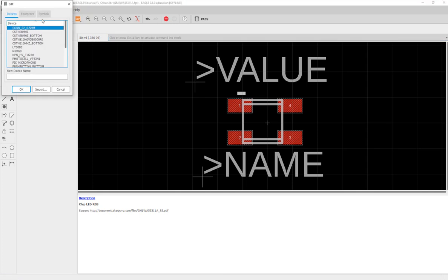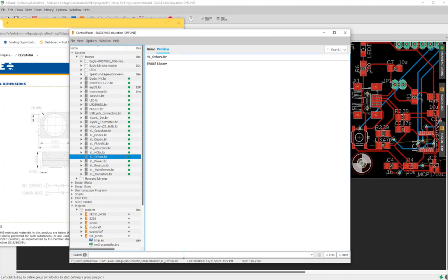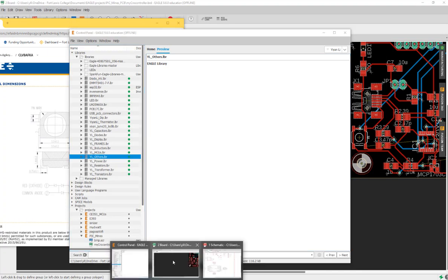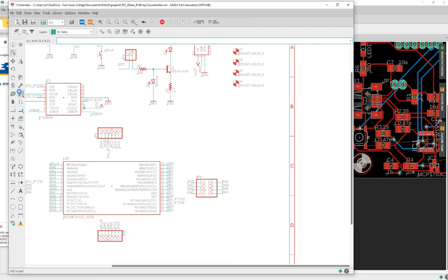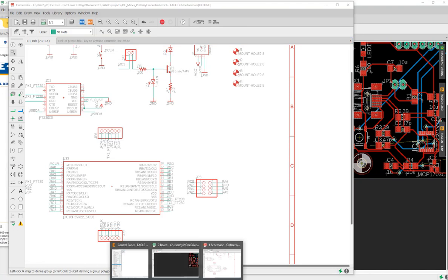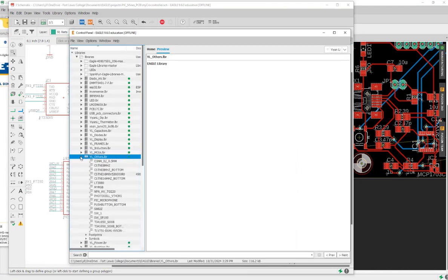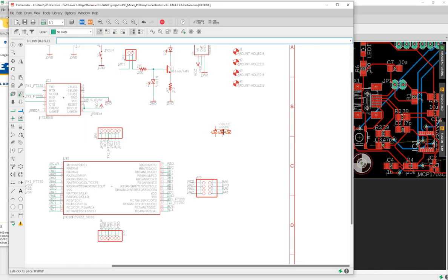If we go to our device, I think we'll just pick up my RGB. Let's close this one. Close this one. And go to schematic and just add it, like the other way that I showed you. So if you do this and go to my RGB, okay, double click, you can add it.